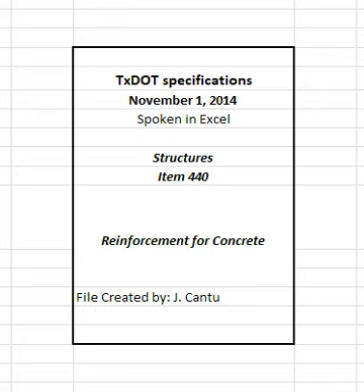Store reinforcement above the ground on platforms, skids, or other supports, and protect it from damage and deterioration. Ensure reinforcement is free from dirt, paint, grease, oil, and other foreign materials when it is placed in the work. Use reinforcement free from defects such as cracks and delaminations.